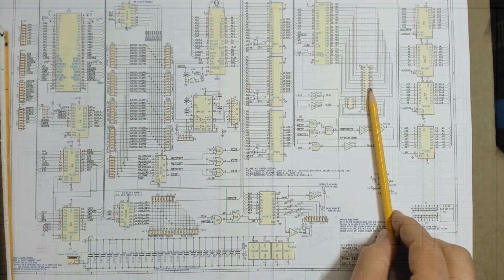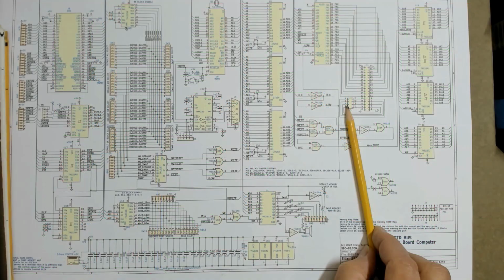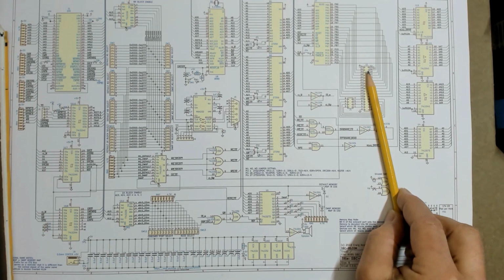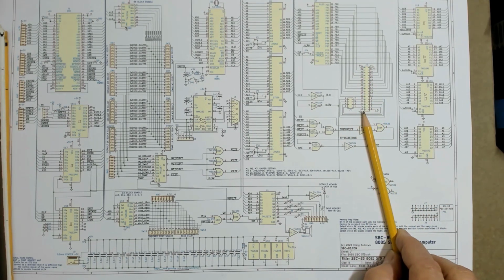So finally, on the 8155, the I/O, you can see that the I/O comes off onto this header, and the header is just mounted up against the top of the board. You can use an IDC ribbon cable to go off to a little proto board or something. There's an additional little patch that also ties into this header. So there's 8 pins here that are designed so that you can go around the board, take some signals you want, either bring signals off or on the board, and those also connect into this 34-pin header that goes off board. So that just gives you the freedom to add some signals that you want to this off-board header.